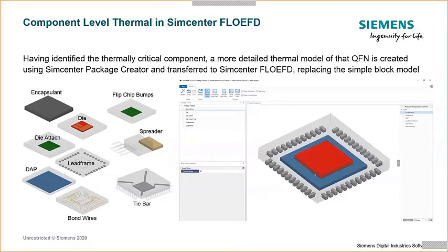So having identified the thermally critical component in Simcenter FlowEFD, a more detailed thermal model of that, or in this case QFN package, can be created using another tool called Simcenter Package Creator. And then that detailed representation of the package can be transferred to Simcenter FlowEFD, replacing the original simple block model.